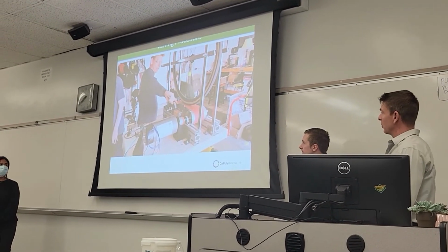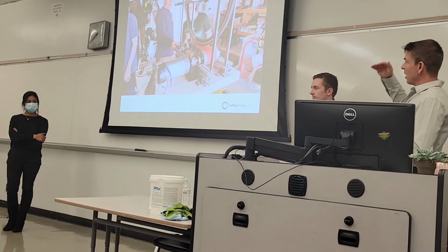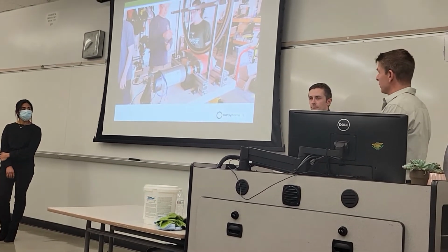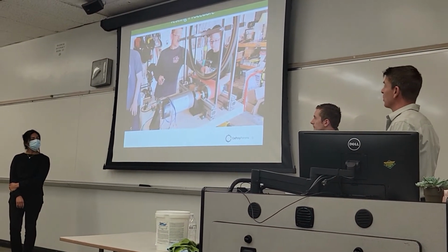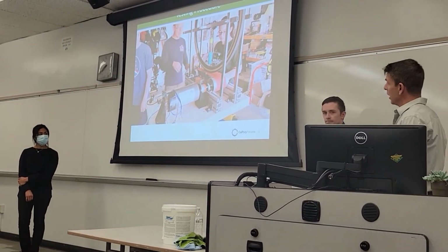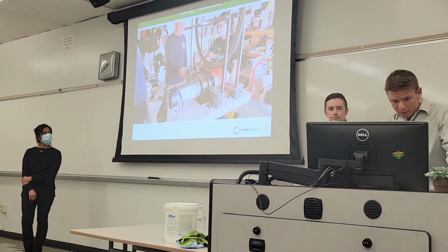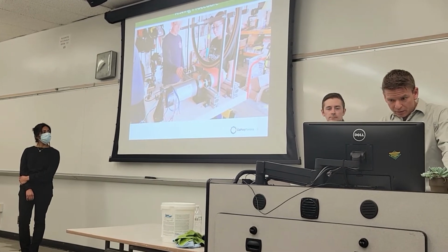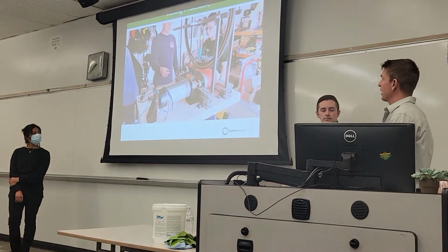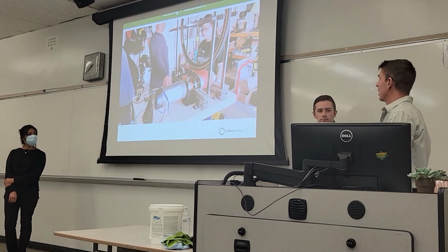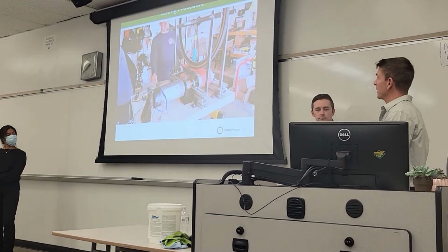During the testing, it's critical to make sure that the belt is aligned, the wheel is operating properly and secured to the wheel block, and to look for any issues with the system as it's moving. So we gradually run the system up to our steady state desired RPMs, and we hold it there for about a minute, and then we end our testing.